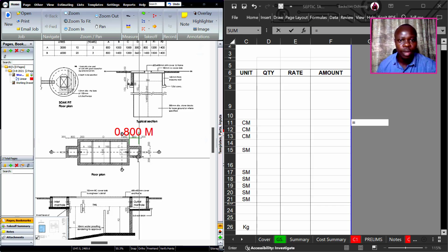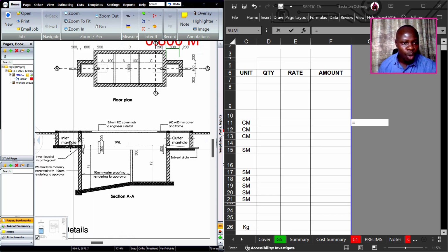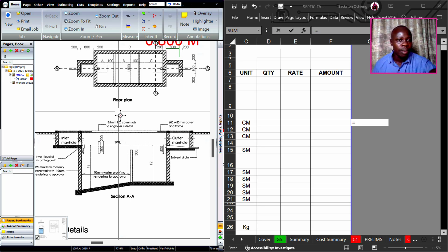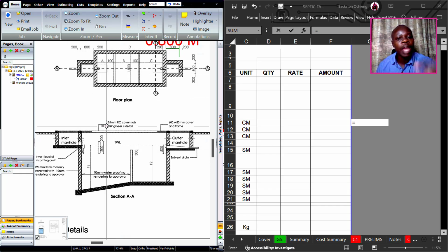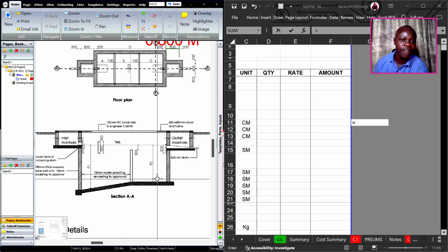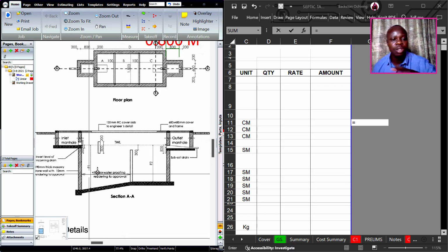getting the excavation. So you can always do this excavation depending on the sections, because you realize that we have manholes on either side. So inlet manhole 1 and also another outlet manhole. But then those two sections, they are not of the same depth as the other one. So you can do it in two ways. So option 1, take the first bigger portion, okay, the portion that has the dimensions F1 and F2. So consider that first, and then you consider the manholes separately. That is the best or the preferred way of looking at this. So on the main section,